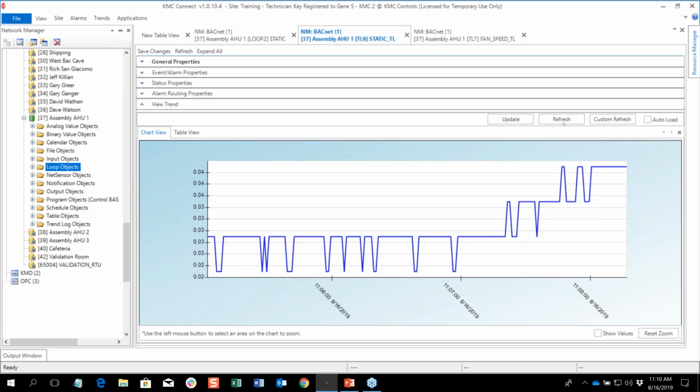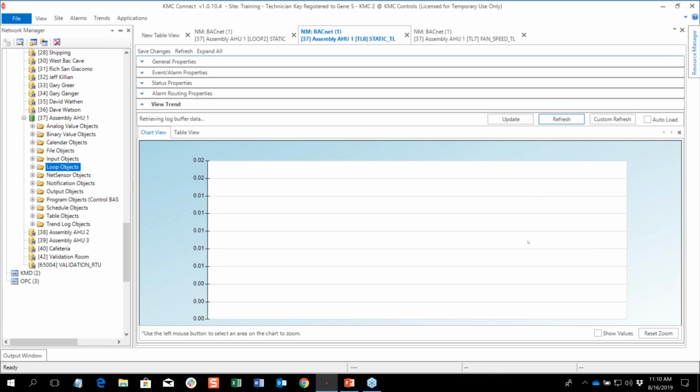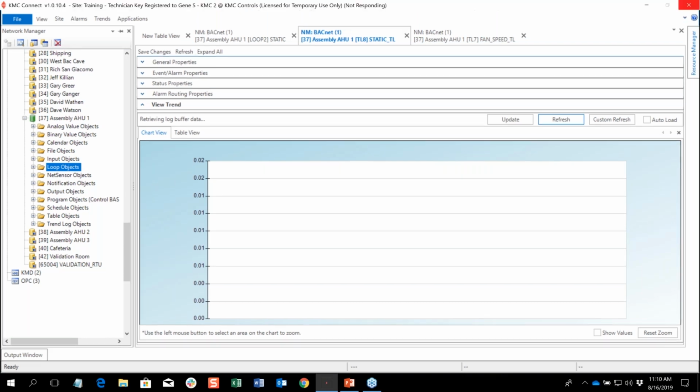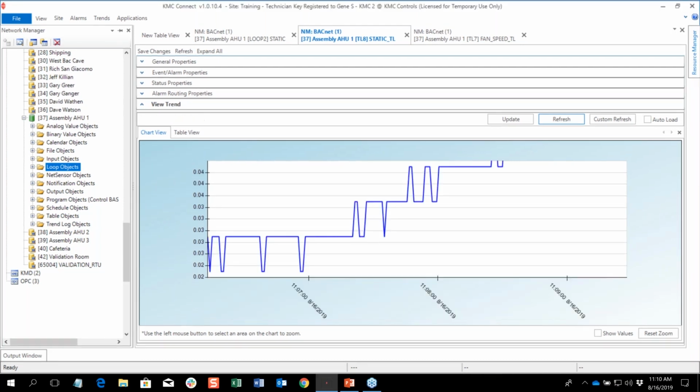In our control algorithm, the proportional term or the gain is carried through to the other terms. So we need to account for that in how we create that number. So if we think in terms of 4 cycles per hour, we need to divide out the proportional band and divide by 100. And that's how we got 0.08.